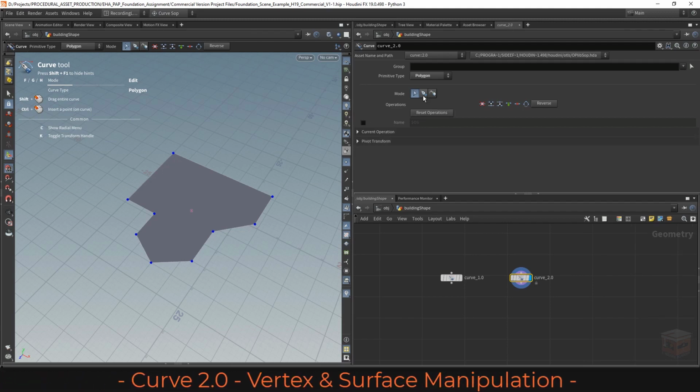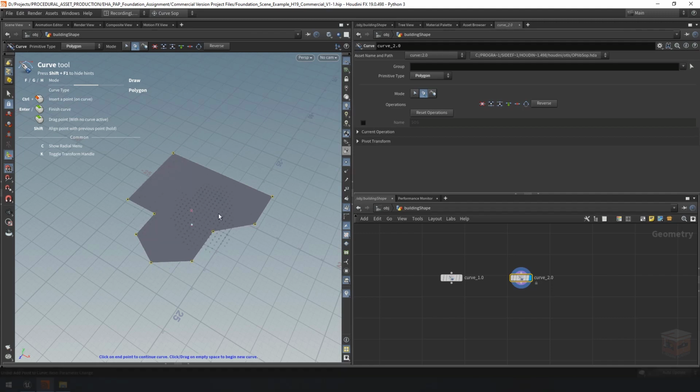So just now, when I created a couple of points and then I connected the last point to the first one, I ended up creating a surface, right? Now, if you don't want that and you want to keep it as a curve, then you can also disconnect one of these points, split it basically, to get rid of the surface and just keep a single curve that starts and ends in the same location but isn't actually connected. Then it won't create that surface.